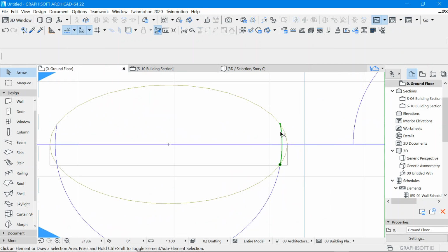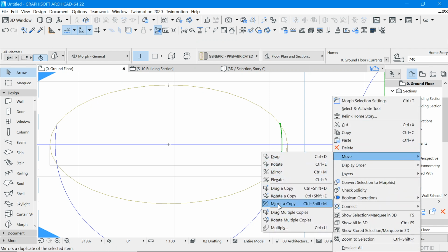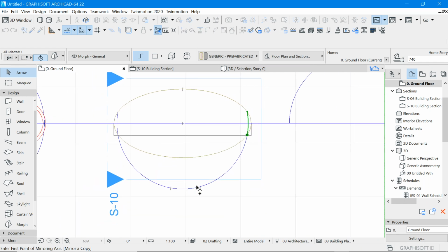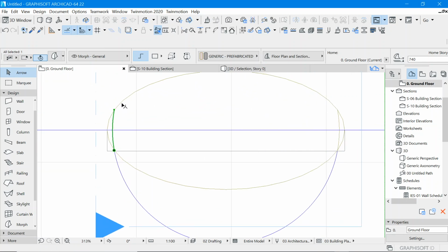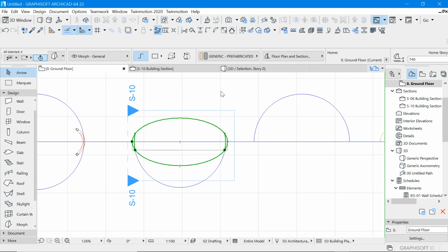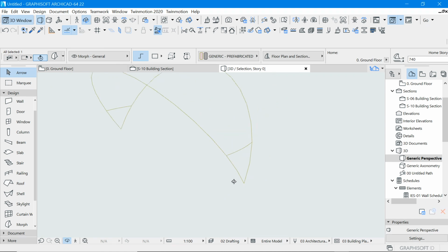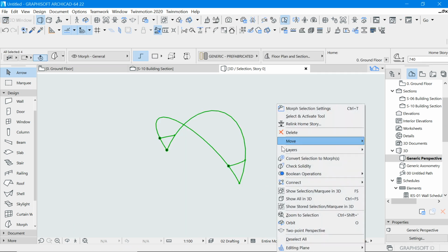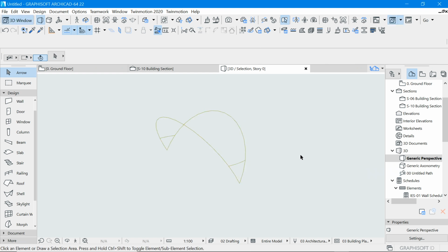and once on ground, make another mirror part. You can use this to help you get the center point. Then you now pick all the 4 Morph elements and then take them into 3D. Once there, just select all of them, right hand click and turn them into one element by uniting them. So once united, go to the Morph edit mode.